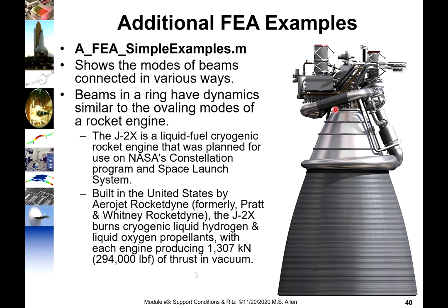But it turns out that at supersonic speeds, a nozzle actually needs to open to cause the fluid to accelerate. So this shape causes the fluid to accelerate, and we want the highest possible speed of the fluid as it leaves because that'll maximize the thrust that we get from the engine.